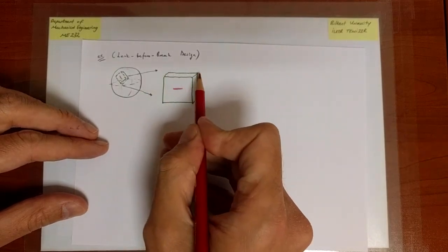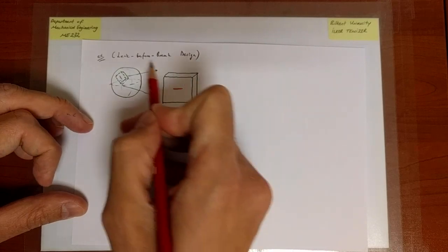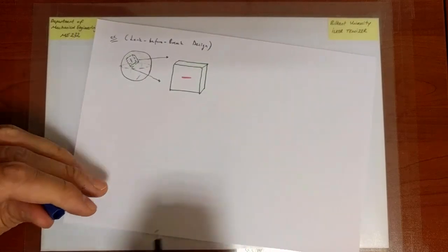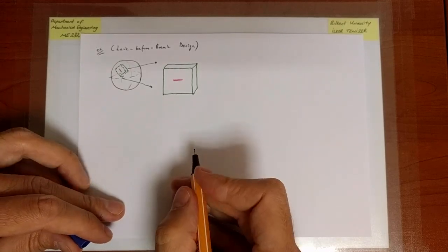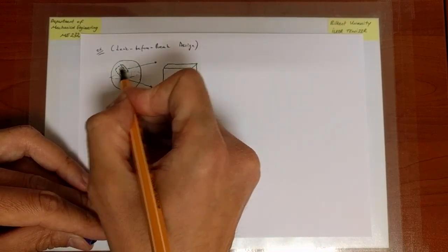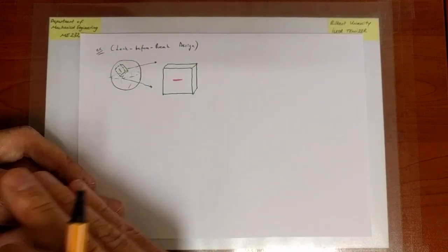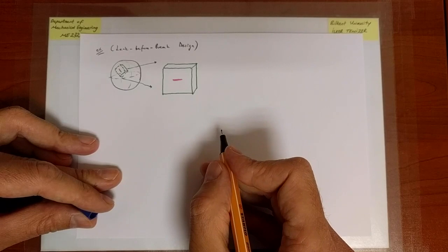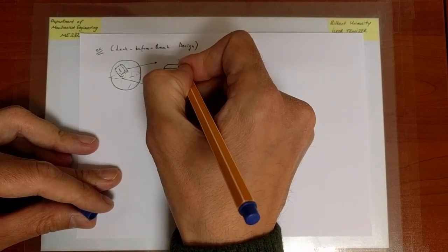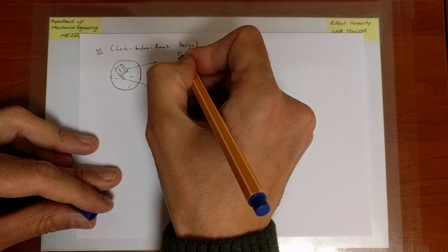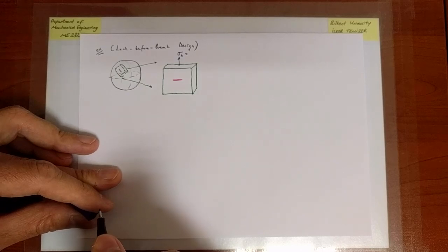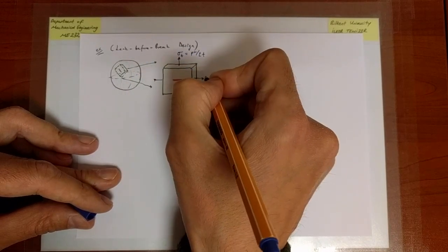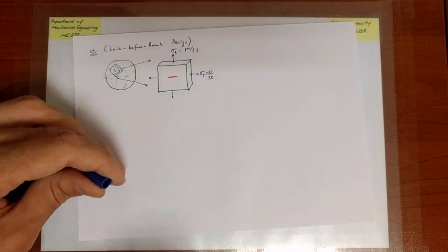Now, therefore, if I'm going to consider the scenario as a fracture scenario, what I am going to consider is a plate with a crack in it. We'll discuss the geometry of the crack a little bit more soon, but what we have is tensile loading. There is an internal pressure, but if it's thin-walled, it's something I can omit. I can omit the normal stress in the radial direction. I'm certainly going to do that here as well. It simplifies my life. But there are two tangential stresses that are equal, which, let me just denote them with a single arrow. There is a tangential stress sigma t, which is equal to PR over 2t, and also another one in that direction. And they are equal because it has a spherical geometry.